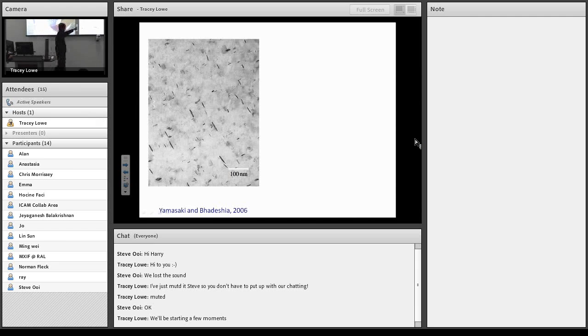Well, this is vanadium carbide particles, vanadium molybdenum carbide particles, which are semi-coherent, and they have strain fields around them. They're designed so that they form traps for hydrogen. So the problem arose that when you make really strong bolts for bridges and so forth, after a while they just break. That's called static failure. And the point in time where they break can be quite scattered. It could be 3 weeks, it could be 3 years. So that's bad. What's happening is that hydrogen gets into the steel from the environment, and this is a really strong bolt, and therefore it's embrittled and it fractures.